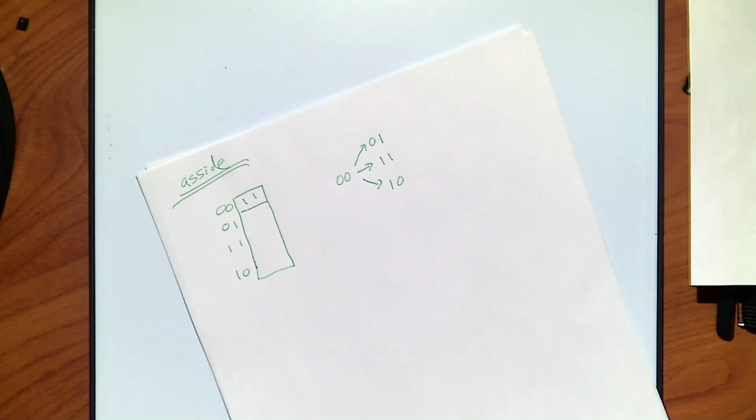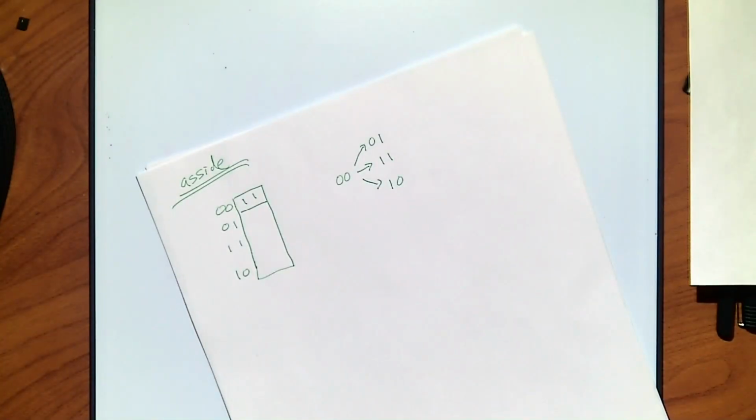Do you remember what we called it when different things could happen, and we're trying to see who happens first? Race condition, right? Races don't only happen with inputs. What we generally want to do is prevent two things from flipping at the same time. In general, it's going to be really hard to happen with your inputs, but you should try to make sure your inputs don't get a race condition. But realize state transitions can have races, and these are blindingly fast.